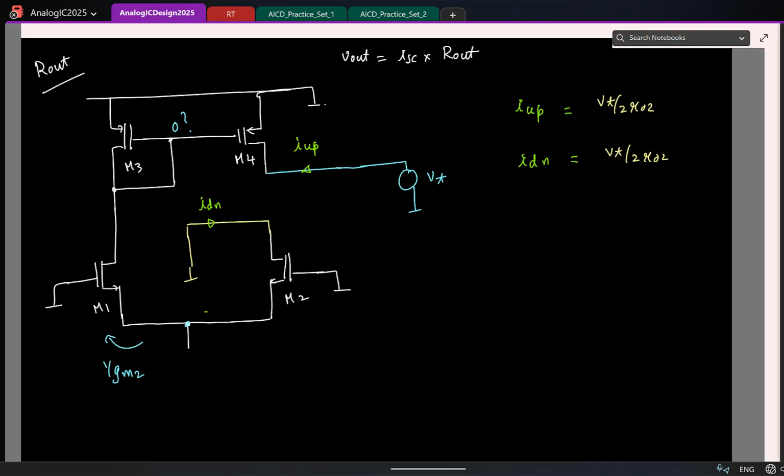Why? Again, this is essentially understanding cause and effect. Current is flowing, but if the VGS has to be set, the difference between the transistor current and whatever current is flowing here has to be fed back to the gate or source. It is like saying I go and have food and then do my business in the toilet, not the other way around.